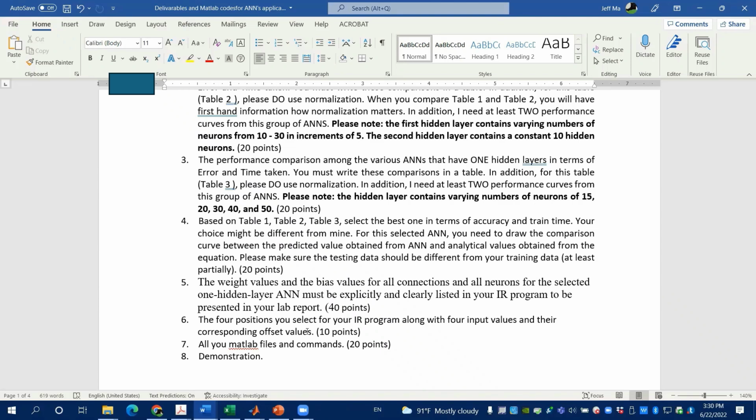If the interaction between the hand and the workpiece is bigger, the hand retracts a larger displacement, and you need to give a bigger offset. This is what we are going to handle: an accuracy problem because of the insufficient rigidity of industrial robots.